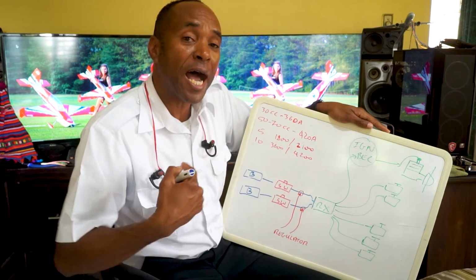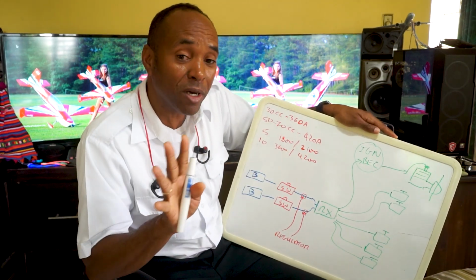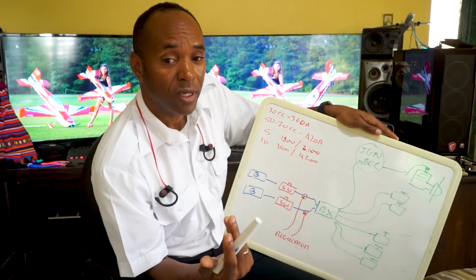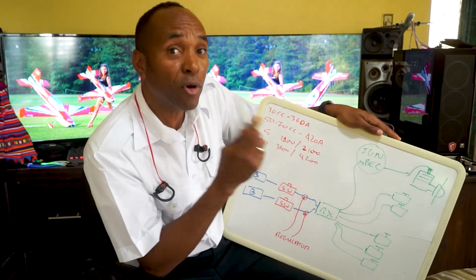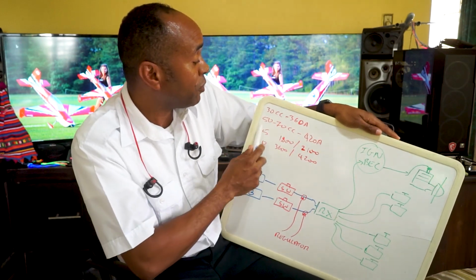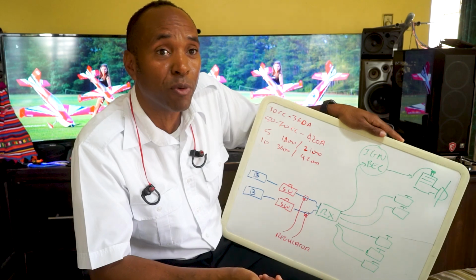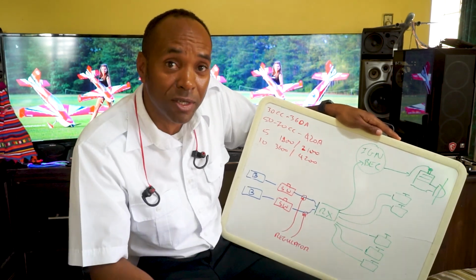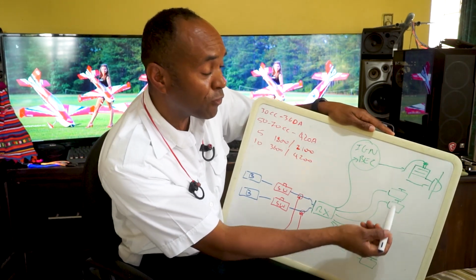Now, what I do for a benchmark is use figures like these. Numbers never lie, right? For a 30cc airplane, each flight will draw approximately 360 milliamps per flight. A 50 to 70cc airplane will draw approximately 420 milliamps per flight. How do I get this? Each servo, for a 30cc airplane, is going to require 50 milliamps per flight.